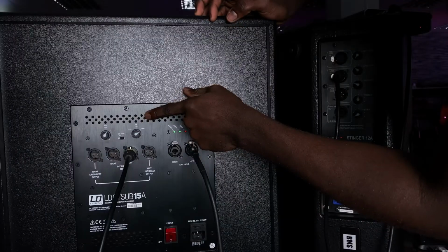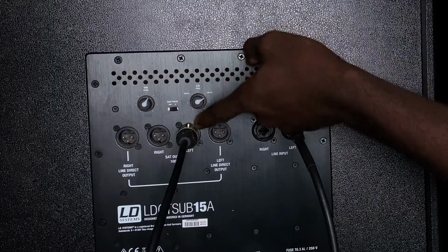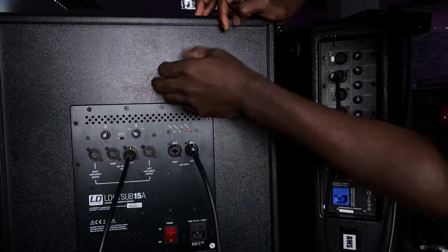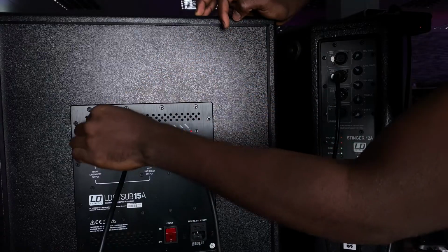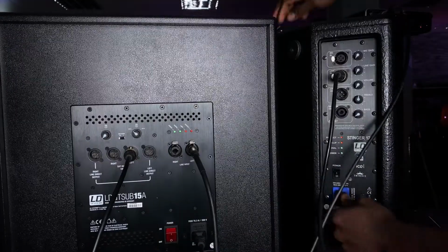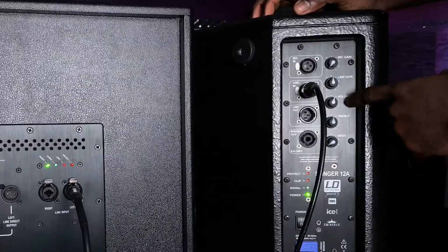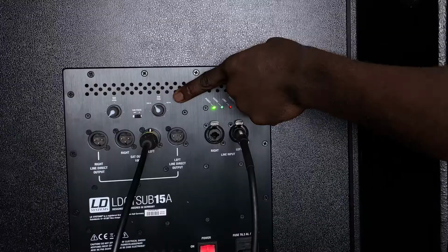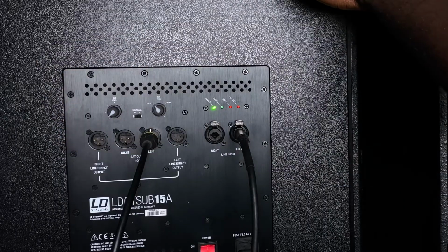This particular subwoofer has a variable crossover frequency, which ranges from about 60 to 180 Hz, and this is the sub level, the level of the signal being fed to the subwoofer, the volume or the gain. Let me turn that down for now. Now let's hear what this setup sounds like. I'll quickly connect the loudspeakers to mains and turn them on, starting with the subwoofer. I've set both the line gain and volume of the full range loudspeaker to the 12 o'clock position. The crossover frequency is set to 100 Hz and the subwoofer level is turned all the way down.